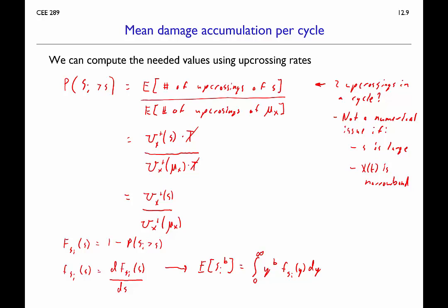And I guess I went by that quickly. In our figure, we were just highlighting the positive stresses. There's a couple ways we could handle this. If we need to think about accumulation of stress in one particular direction, say accumulation of tensile stresses accumulating damage, then we can just call that direction positive. If the absolute value of the stress is interesting, then we can think about taking the positives and the negatives. There's just an adjustment we would make there, but conceptually it wouldn't be dramatically different.